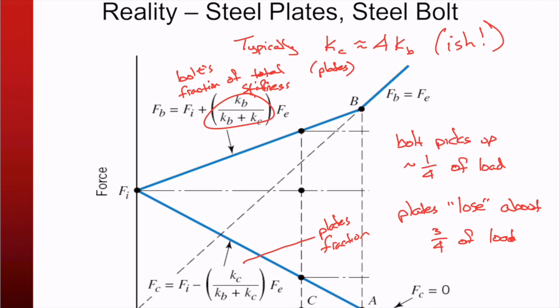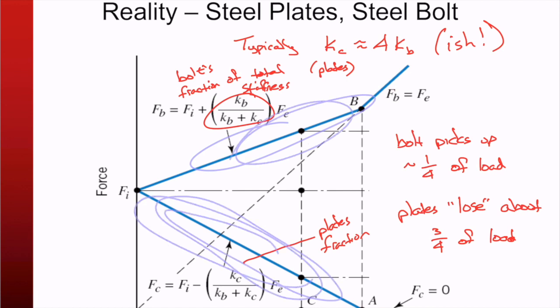So that's the subtle relationship. As I stress a clamped joint, the bolt picks up some of the force, and the plates get reduced, the clamping pressure gets reduced.